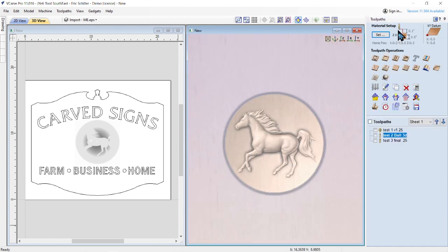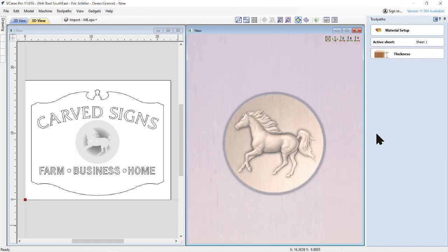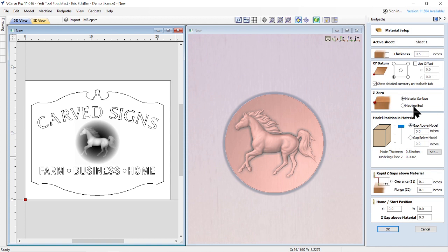When I first got the job in, I went to material, I highlighted the 3D object, and it's not positioned below the top of the material. So what I would do is position it below. I'd also set a zero plane so this outside rim is cleaned up a bit. Without that, depending on how you're optimizing the cutout, you can have some jaggies around this edge. So here's what I would do.